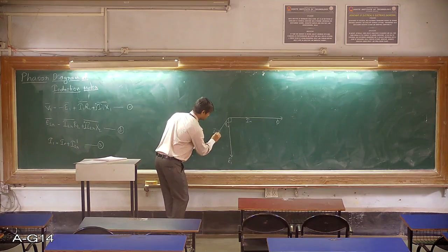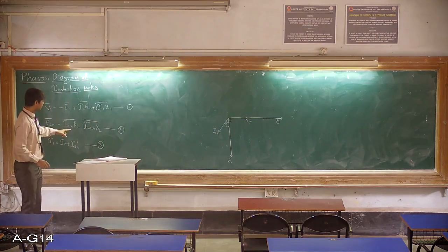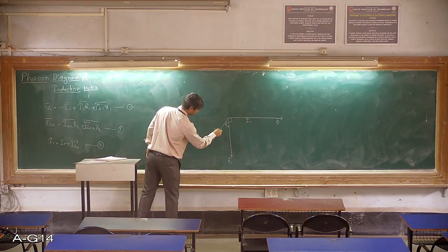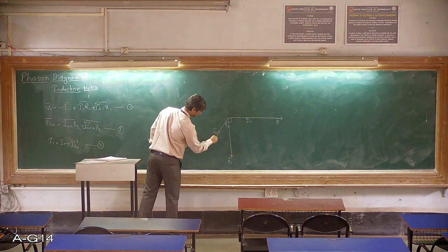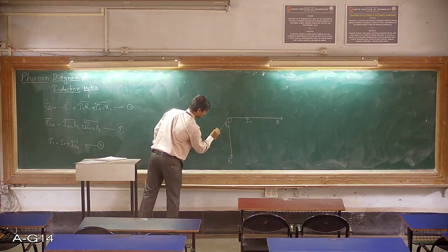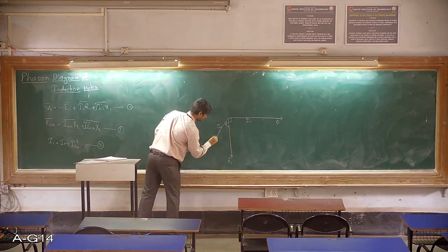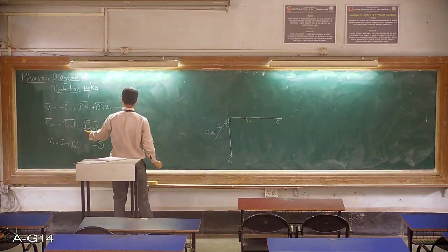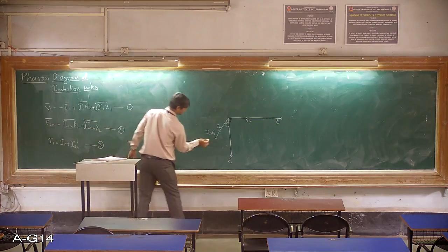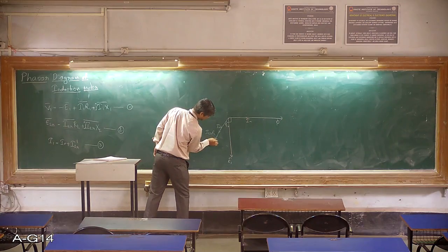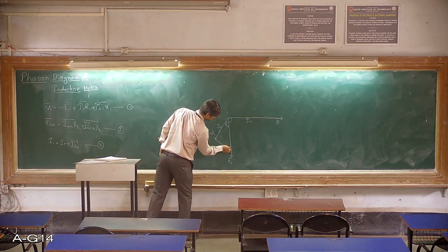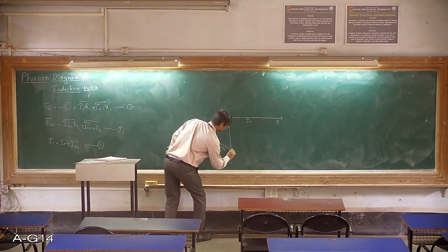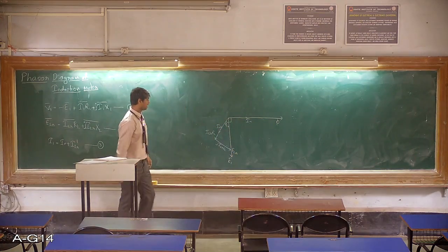Now after this, we know that E2r is I2r R2 plus j I2r X2. So I2r R2 will be in the same direction, in phase with the I2r. So here I extend the line, and this is I2r, this is I2r R2. Now this is I2r R2 plus j times I2r X2. J times I2r X2 will be 90 degrees to this I2r line. So here I have j times I2r X2, and this is nothing but our E2r.